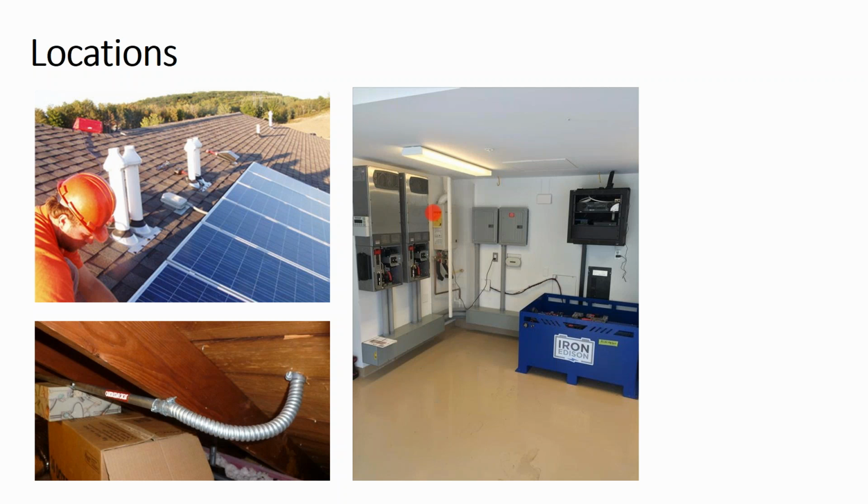And yeah, you may need to think about putting in a box upline for wire terminations. Maybe that external disconnect switch is actually not such a bad thing, because you can have water weep out of that disconnect switch rather than going into the inverter. But technically, you're supposed to seal this between the hot environment and the cold environment to avoid that airflow, avoid that condensation accumulating inside the conduit to begin with.